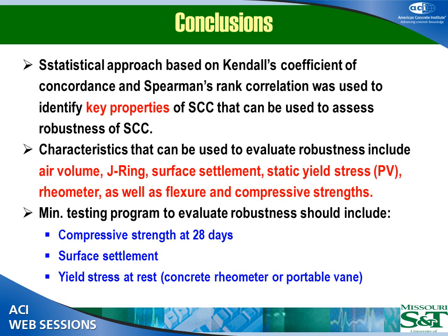Yeah, if you look at the coefficient of variation, for example, on any rheological property, they were very, very sensitive. Again, we are dealing with concretes that go from a water-cement ratio point of view from 0.35 to 0.39. So your fresh properties would be very affected. In some cases, for example, you are not getting self-consolidation. You might get blockage in the J-ring. In other cases, on the extreme side, you might get bleeding and segregation. But in terms of mechanical properties, because the window is so little, when you are measuring your 7, 28, 56-day mechanical properties, the variations were not that high.